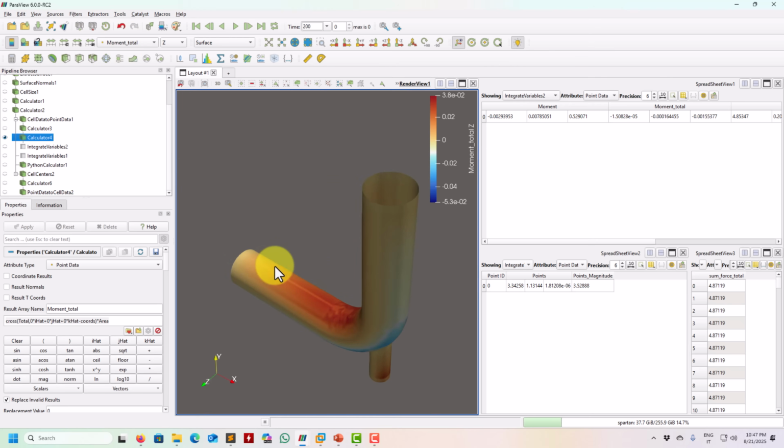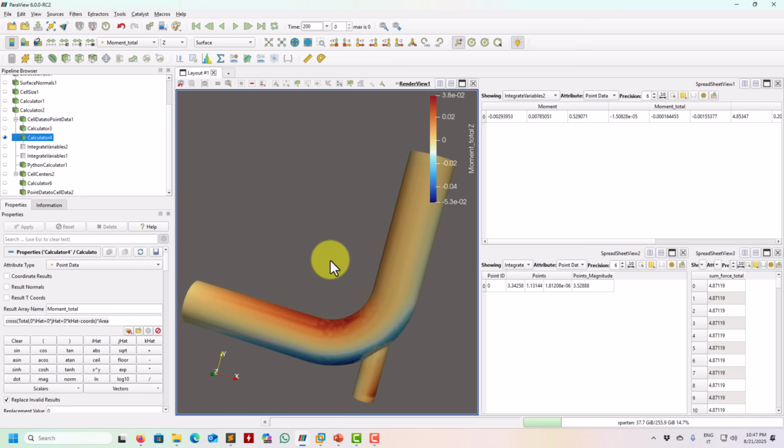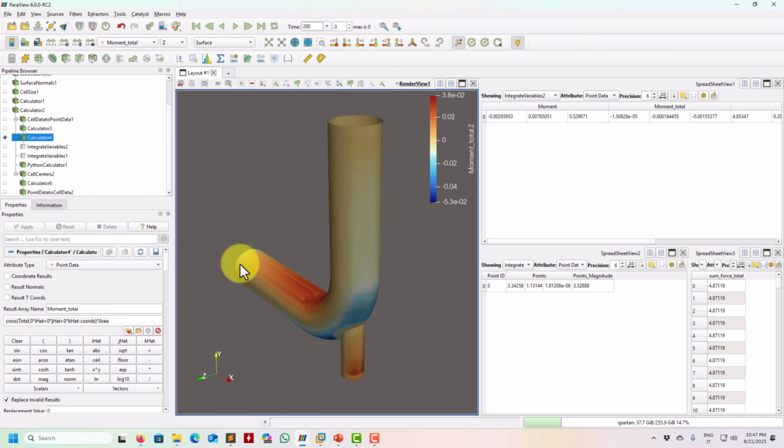And then probably also if you want to do cut planes and plot on those lines the forces distribution, as I mentioned, like the span-wise distribution of lift and so on. That's the only reason, but for the rest, if you are just interested in total forces, just rely on your solver, whatever you are using. This is it, and pretty much it works the same for unsteady data. So probably we'll prepare another case, on unsteady, but it's exactly the same.